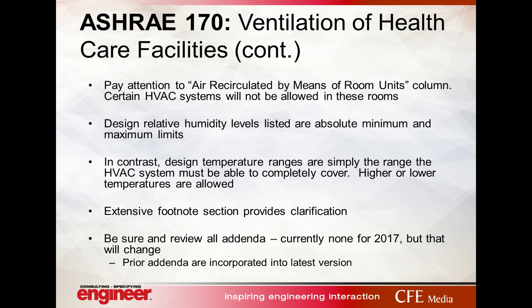The temperature requirements, on the other hand, are different. They're not absolute maximums and minimums. They're ranges that your system must be able to hit while staying in the humidity range. So the operating room temperature range on the chart is 68 to 75, but I've never met a surgeon that's happy at 68. They always want it colder than that. The fact that the chart says 68 to 75 doesn't mean you're not allowed to go below that. It means that your system has to be able to hit that range. But just keep in mind that you're allowed to go out of it, and will often be required by user requirements.